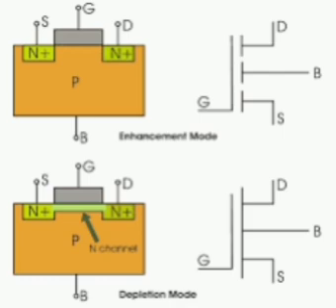Saturation means VGS greater than VTN and VDS greater than VGS minus VTN. IDS equal to half mu n COX W by L into VGS minus VT whole square into 1 plus lambda VDS. Lambda means channel length modulation parameter, VTN means threshold voltage, mu n means electron mobility, COX means oxide capacitance, W, L means width and length of the MOSFET.